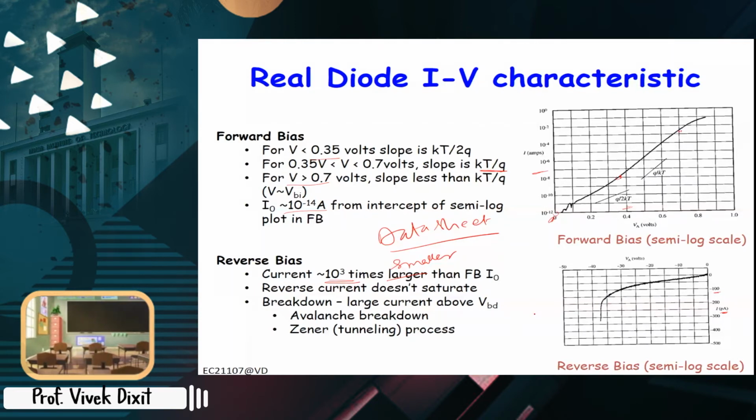There are two breakdown mechanisms, avalanche and Zener. Avalanche is basically due to high energy electrons and holes. These bonds are broken and electron hole pair is released. Zener is basically tunneling. Now tunneling will happen when the barrier is narrow. Now in which case the barrier will be narrow? Barrier is actually your depletion region, you can say, right? Now in which case the depletion region will be narrow? When doping is high, right? So Zener tunneling is usually seen for high doping. Now let us discuss them one by one.